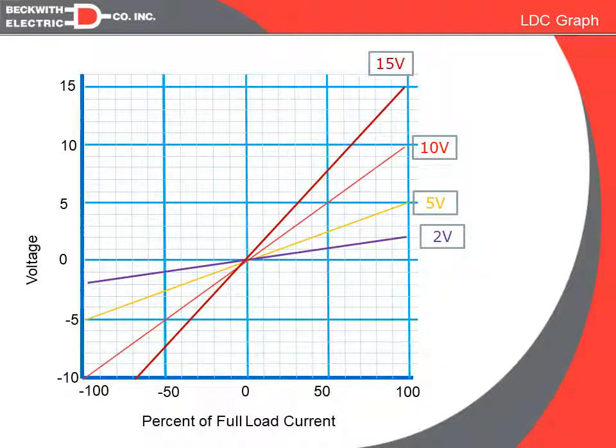But the general rule of thumb is if you're selecting ignore or DG mode, then in those two modes we're saying the source is still the source, and if we see current come in reverse, it's because it's coming from the load into the source as opposed to from the source to the load. And in that case we would want to flip the signs in the forward and reverse settings.